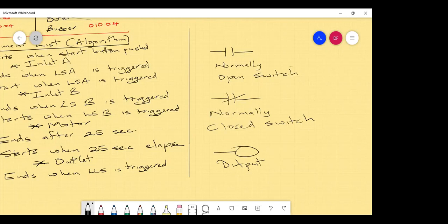All right. Okay. So you trigger the switch, it turns off. Hold on. Sir, normally open, just to clarify, when the switch is in its normal state where it's not energized, it is in an open state, correct? Right. And so when you energize it now, it closes. Yeah. And then normally closed is that when that switch is not energized, it is shut. And then when you energize it, it's open. Right.